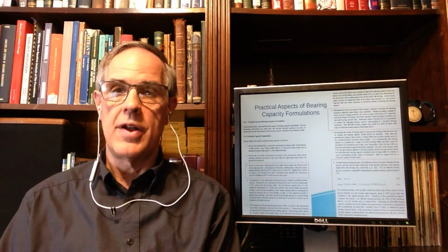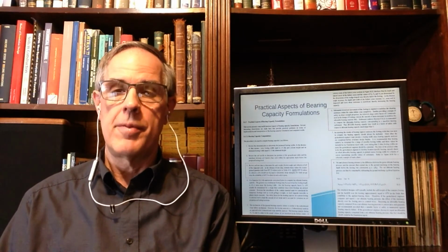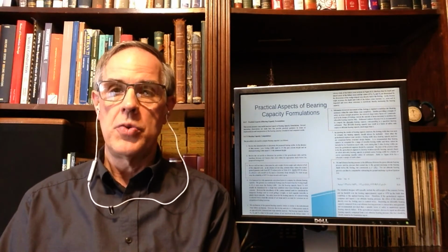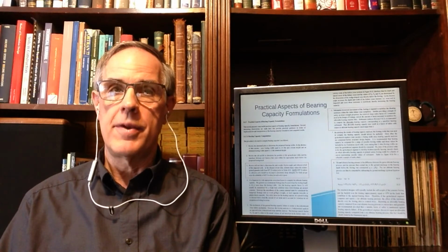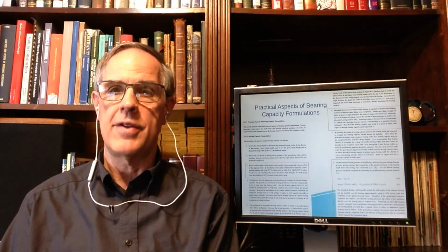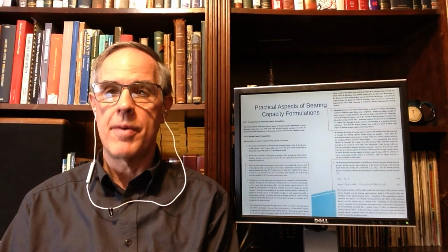As a result, it is very advisable to run a settlement analysis, and particularly as the foundations become wider, you will discover that the settlement analysis basically drives the design as opposed to bearing capacity. So that's something you should keep in mind.